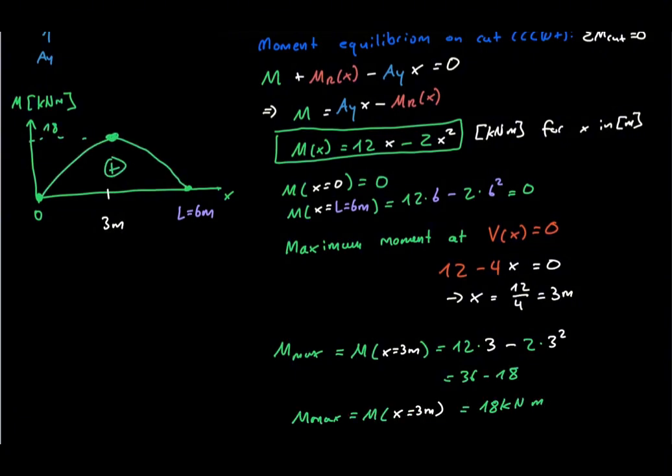The most important lesson from this example is that the loading has not changed, but the support conditions have. Those support conditions completely change the support reactions and, as a result, the internal force diagrams.